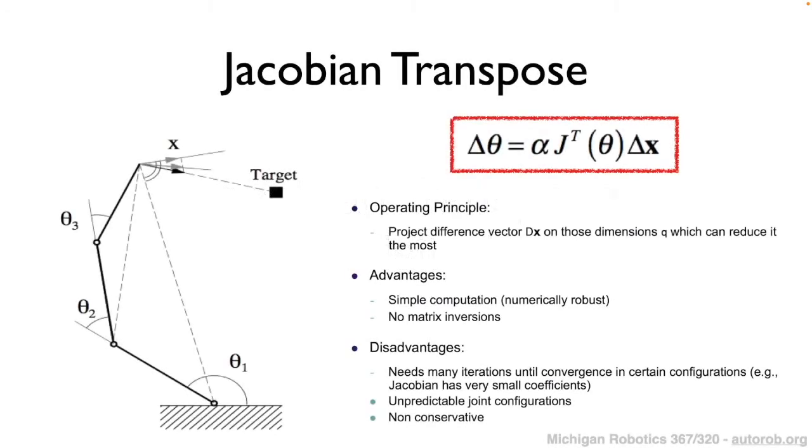This brings us back to the Jacobian transpose that we looked at the start of this discussion on inverse kinematics using optimization. In particular, what the Jacobian transpose proposes is defining this step in configuration space to be equal to the Jacobian transpose, based on our current configuration, multiplied by a displacement in the end effector pose, as opposed to the Jacobian inverse.